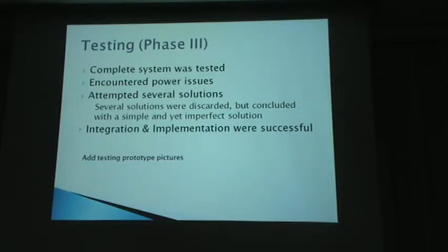What we had in mind is that if we put the parallel connections, it will give enough voltage to all the devices, and whichever device needs however much current, it will pull that current automatically. Because we needed about 650 milliamps for the whole complete system, and the battery supports that instantaneously.